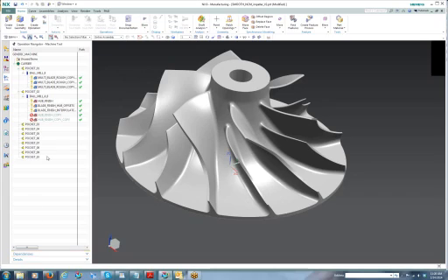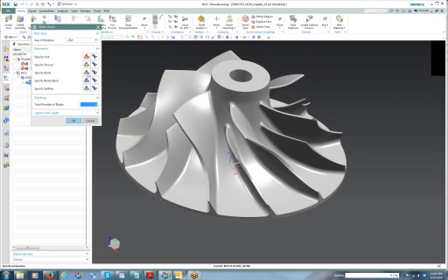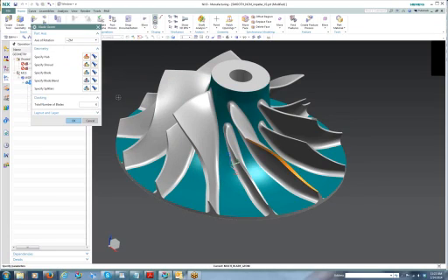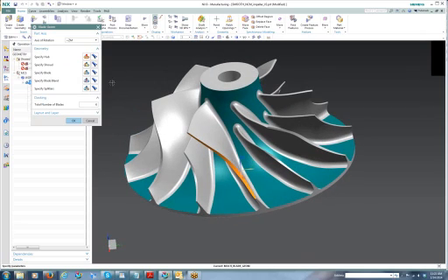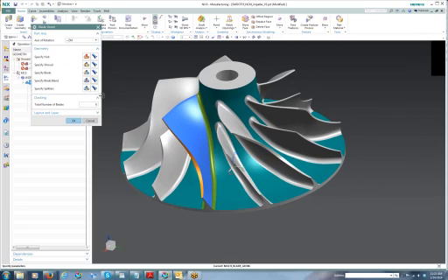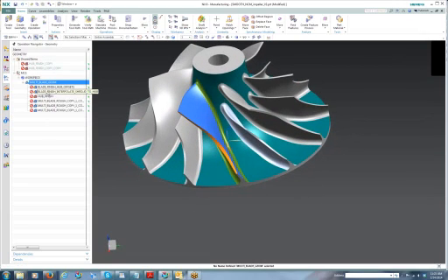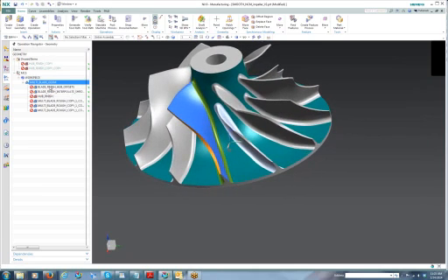If we look at our geometry view here, you'll see that to set up a blisk like you see on the screen, we specify the hub, the shroud, which we've specified by picking up only one of these faces, and then one of the blades, the blade blend at the bottom, and then here's a splitter, the smaller blade, is also defined. By defining only that geometry, we're then able to apply our specific operations. And so here you're going to see Swarf machining and a couple of our other techniques.